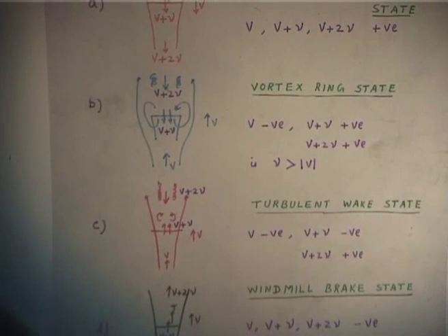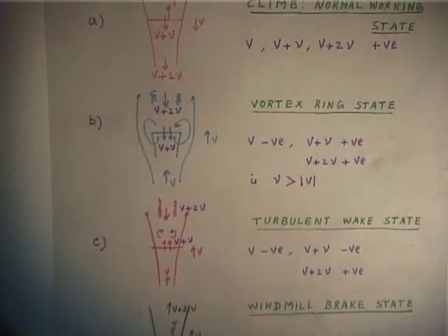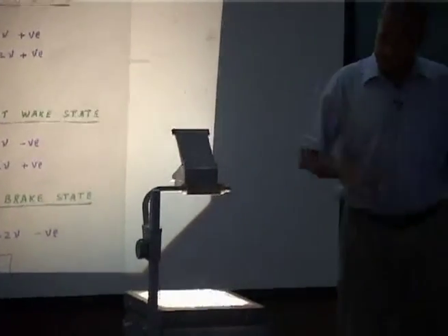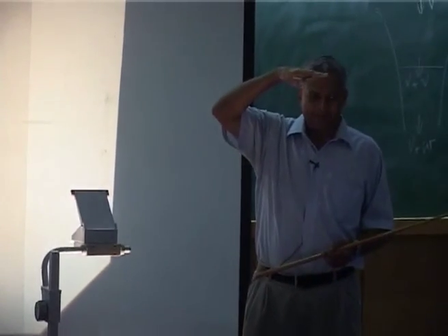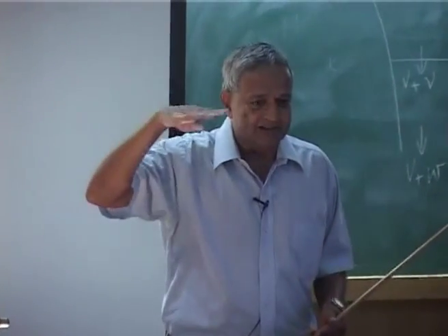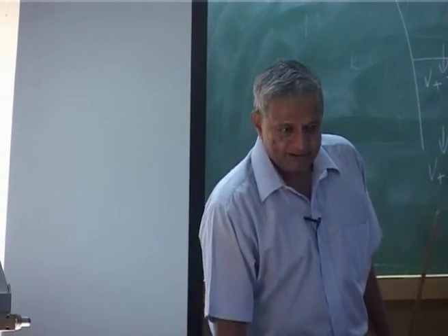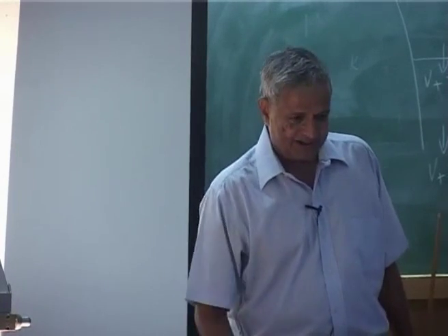So, it is equivalent to velocity coming, but then at the rotor disc, because the rotor is still supporting the weight of the helicopter, which is equal to T. For it to support, it has to push the air down. Okay. That is how the rotor is doing the work in pushing the air down, that is how it is staying. So, at the rotor disc, the rotor is pushing the air down, but from the far field the flow is coming up. You understand?